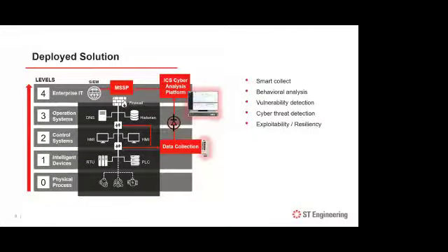When it comes to the asset discovery, it will provide information like how the OT devices are connected in the OT network topologies, which devices can be found in the OT network, information like IP, MAC address, and even the firmware and the brand of the OT asset. Thereafter, it also provides the vulnerabilities associated with each of the devices.